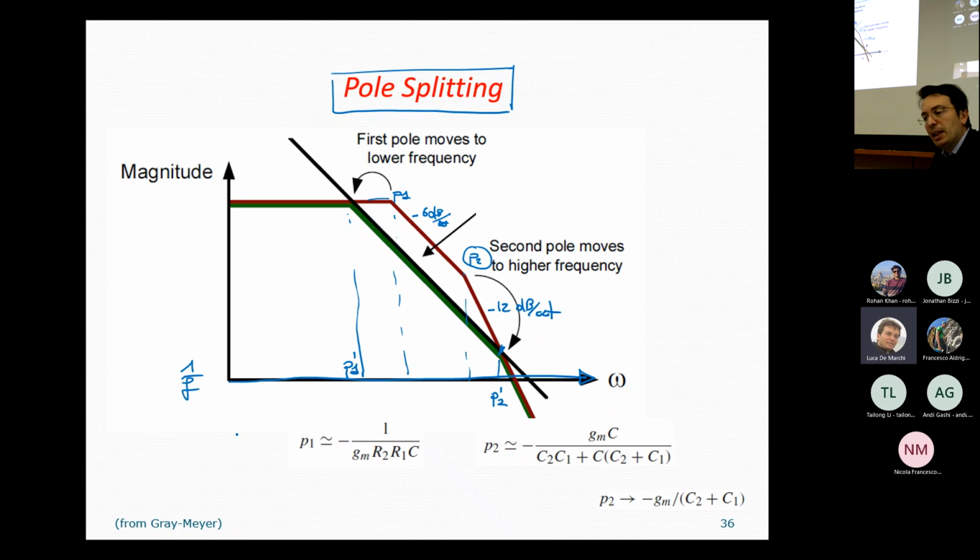Allora, okay. So another important specification for these designs is the one related to the slew rate. Okay, so the capability of quickly increasing or decreasing the output value. So this is basically related to the maximum of the derivative of the output value with respect to time.